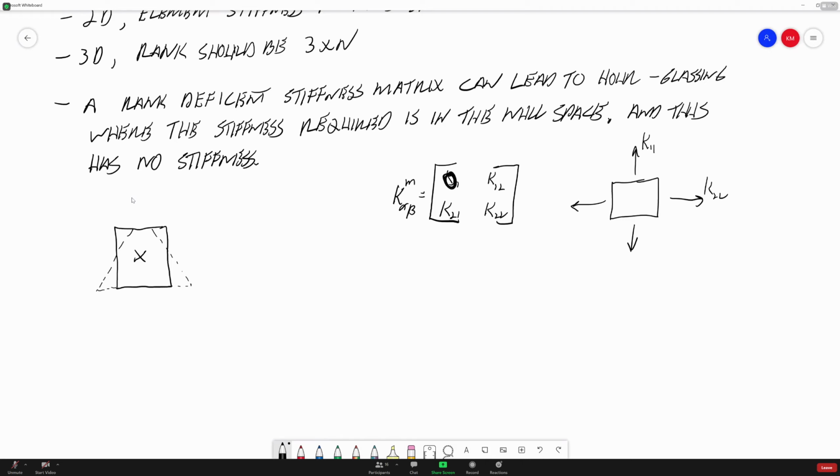What we shouldn't have happen with these elements is they should change shape, but they shouldn't lose any volume. So if you have something in your stiffness matrix that has gone wrong, you have a 0 where you shouldn't, or you have an improper number of integration points with your element, you can get a negative volume, and it's called this hourglassing effect.